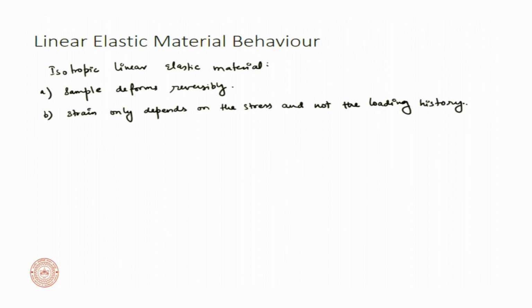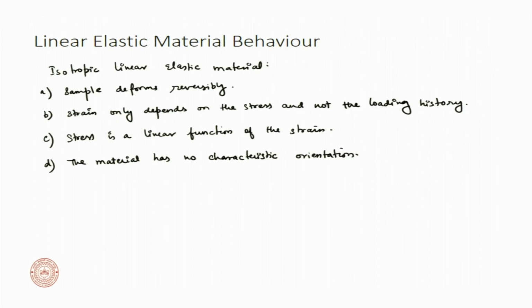So, what I mean by that is that the body does not care how many times you have loaded or unloaded the sample, at what steps the forces have been applied. It will only look at the instantaneous stress, and that instantaneous stress will give you the strain at that point. Okay, so, it does not depend upon the stress history. You can take it in one shot, you can take it in steps, you can take it with any other curved path possible.